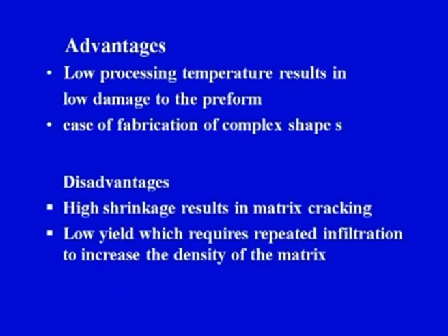Now what are the advantages of this process, sol gel? I have already told you we are not discussing this process in detail because it is quite similar in principle to the liquid infiltration process, where the preform is there and the liquid infiltrant is there. We have understood it with the help of a diagram. There is a piston, the piston presses the liquid infiltrant, the infiltrant goes and fills the open spaces inside the preform and forms the matrix.